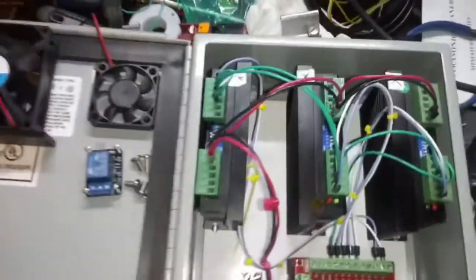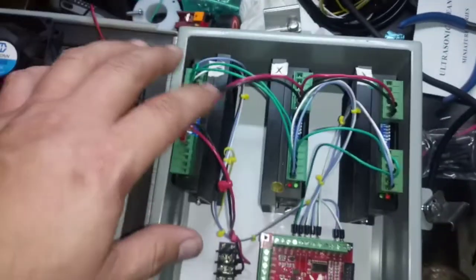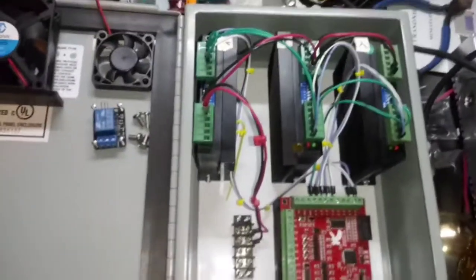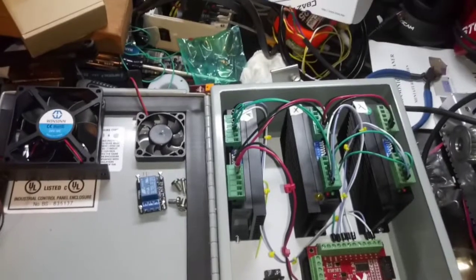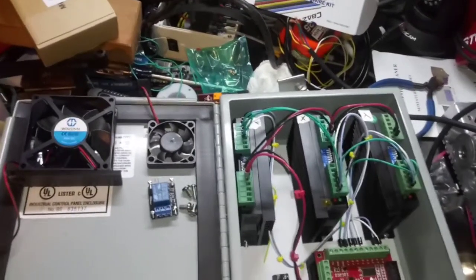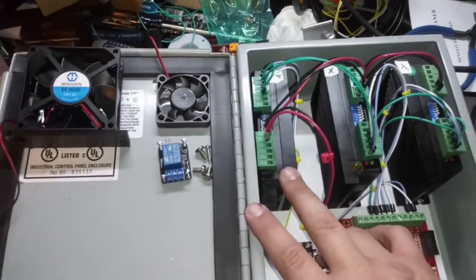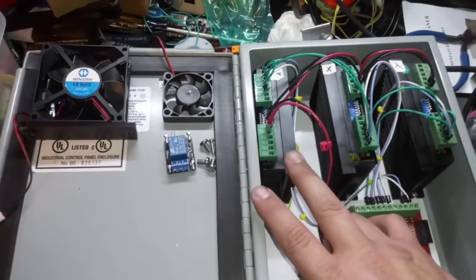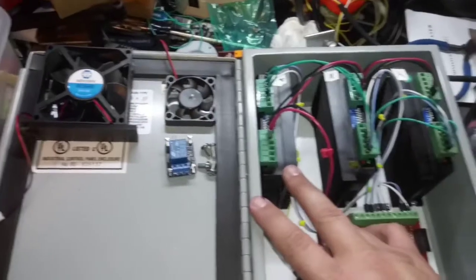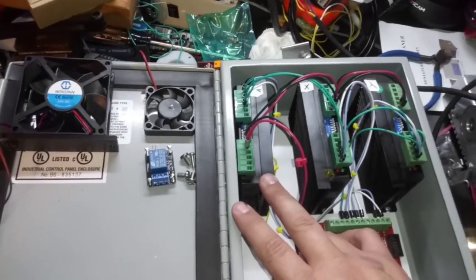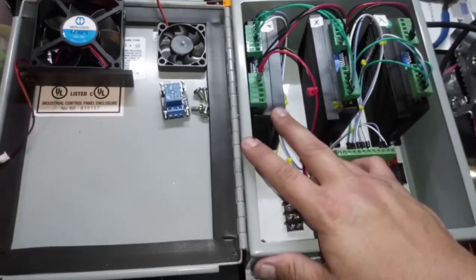You probably see that I've got X, Y, and A axis here, and of course, the benchtop mill on my desk that I'm converting, I'm not using the Z. I'm not going to convert the Z to CNC. So I have the A here for the dividing head. I'm going to put a stepper motor on the dividing head to make kind of a 4th axis, but I suppose on my mill it'll be a 3rd axis because I don't have the Z. Alright, now that we're all confused, let's keep going.